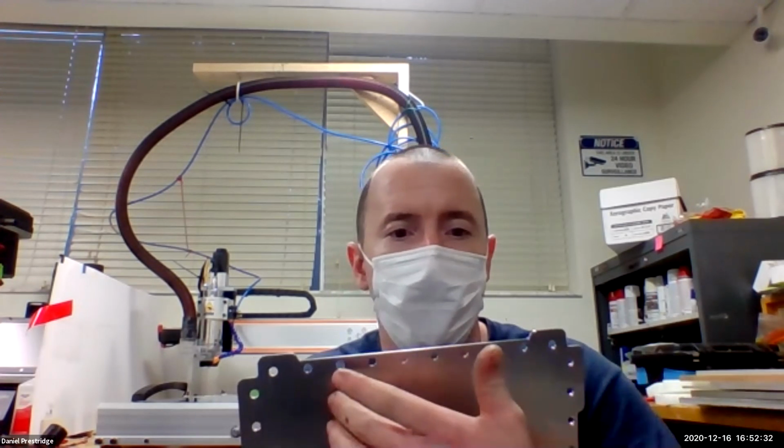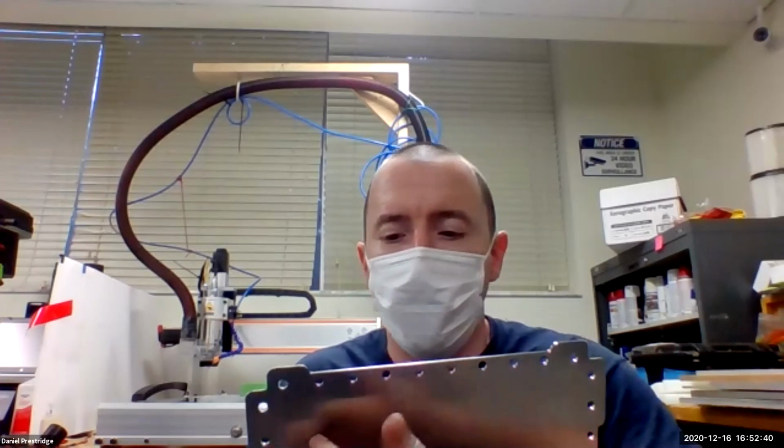For instance, if I'm holding this down with tape and glue, which is one of the methods I like to use a lot, where you literally put tape, glue, and then another tape on there and put it down, it holds really well. But if you run your passes and end up accidentally cutting out in the middle of where you're doing your work holding, the last thing that you're going to cut, it's going to launch that piece.